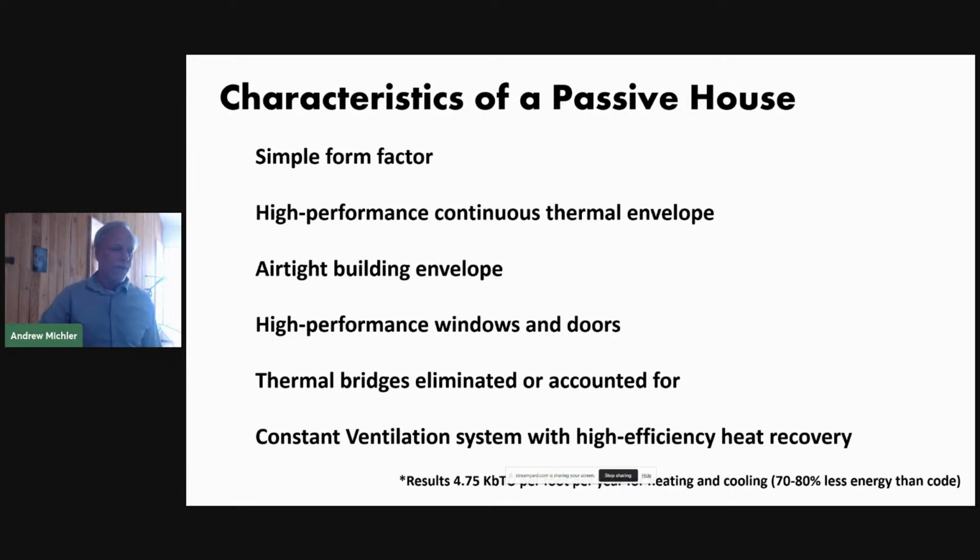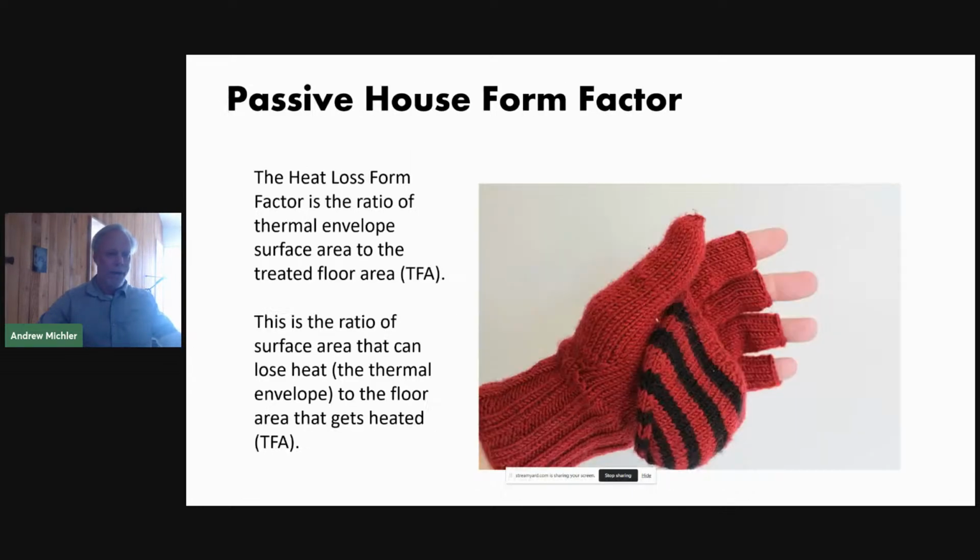And then, of course, the constant ventilation system, the heat recovery or energy recovery system. So we constantly are replacing the air in the building, but we're grabbing that heat or that tempered air from the building and putting it into the new fresh air. So we don't have a huge energy loss while we provide that fresh air system.